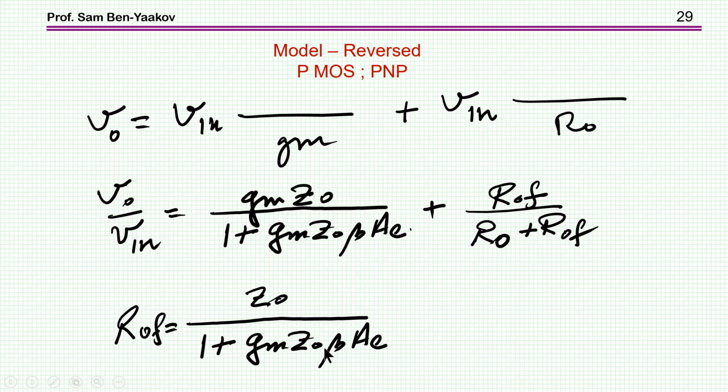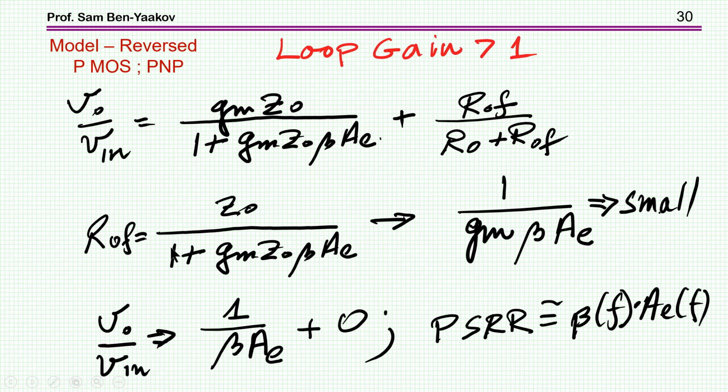So this is the full expression for the injection from V in to V out. I'm expressing it here as V out over V in, so it's actually 1 over the conventional power supply rejection definition. So now I'm dividing the operational range in terms of frequency into two ranges, one where the loop gain is larger than 1, and then, of course, when it is smaller than 1.